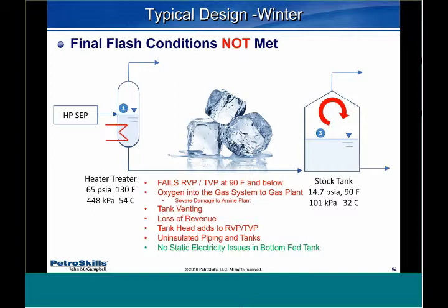So you have the equipment, the hot stuff, way far away from the cold stuff, and all the pipes uninsulated. And what happens is that little packet of fluid that starts here at 50 pounds and 120, it's still in the pipe, but it never gets to the tank to make the final flash at 110 in atmospheric.